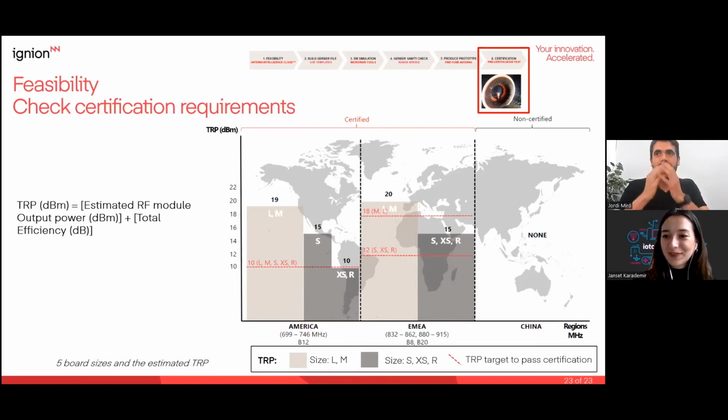Okay, let me remember the marketing class. No, the name Virtual Antenna is because our antennas are non-resonant. It means that it is not only the antenna, the red part, it is a system. The antenna works thanks to the matching network, but also thanks to the ground plane layer, being a non-resonant system, and your PCB is radiating with the ground plane layer. That is why it is a virtual antenna: the red product is not the whole antenna, the antenna is the system. Okay, perfect. Thank you.